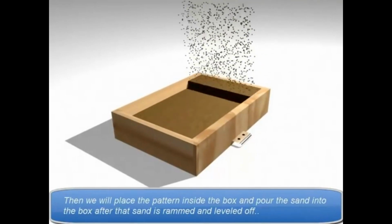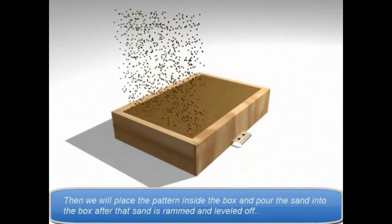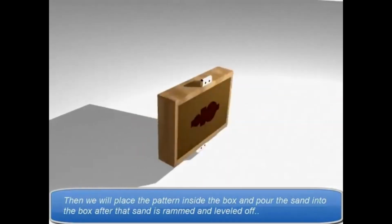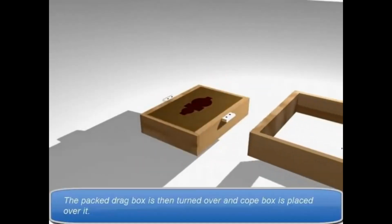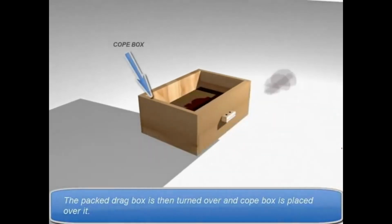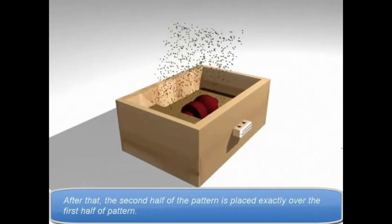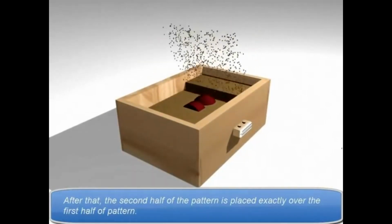After that, the sand is rammed and leveled off. The packed drag box is then turned over and the cope box is placed over it. After that, the second half of the pattern is placed exactly over the first half of the pattern.